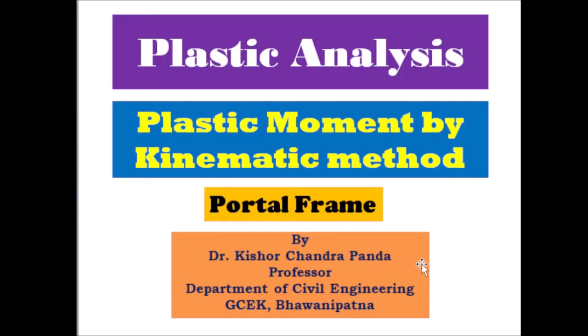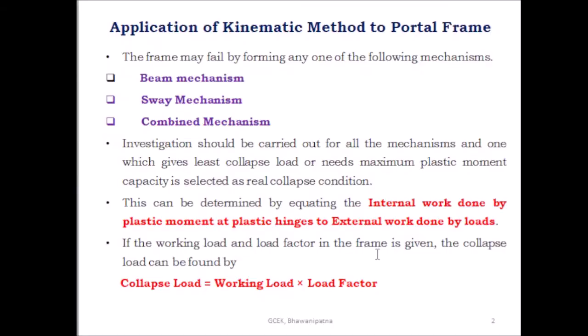In this lecture, I am going to present what are the different types of mechanisms found for failure of the portal frame and how to determine the plastic moment of a portal frame by kinematic method. Then I would like to solve two problems based on the portal frame. Then coming to the application of kinematic method to portal frame.